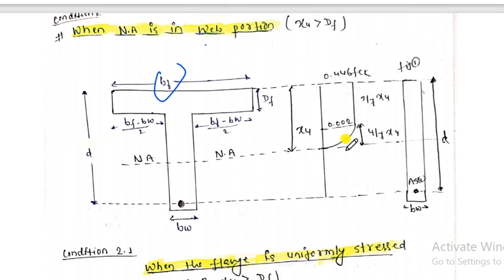Neutral axis. So here I have initiated a diagram, right? Up to 0.002 it will follow parabolic action. After that it will be constant and form a rectangular block, and this one is the parabolic block. So from the top up to the neutral axis, the depth is XU, and from 0.002 to above, that is 3/7 XU, and from there down, 4/7 XU. We have also derived 3/7 XU and 4/7 XU in the previous lectures only.